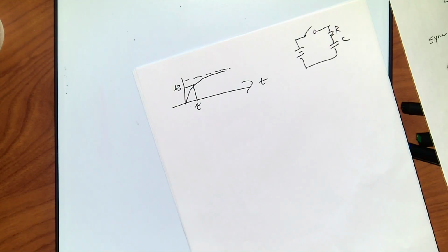And then what's left over, the remaining 37%, in the next time constant you get to 63% of that 37, added on to it. Which is why you can keep going out with time constants and it gets smaller and smaller. At what point is it good enough? We usually say 4 is close enough. That's a heuristic, but it works pretty well. But it'll depend on your system.